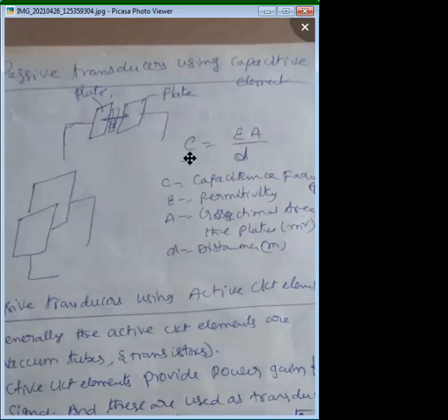as passive transducers. In all such situations, we can use a carrier signal as some excitation voltage, and with control of that excitation voltage, we can identify the variation of the capacitance by using some deflection meters, as we can see in a Wheatstone bridge. A deflection meter will be fixed in between the terminals, and the variation of the capacitance will be measured. One of the capacitance measuring bridges is the Schering bridge, and for inductance measurement it is the Hay bridge.